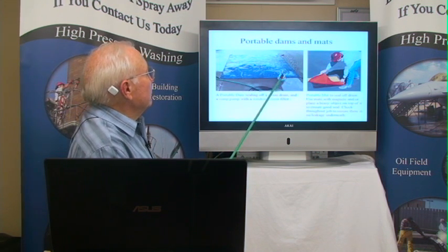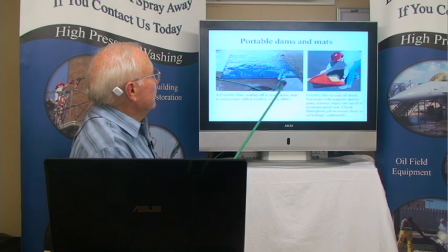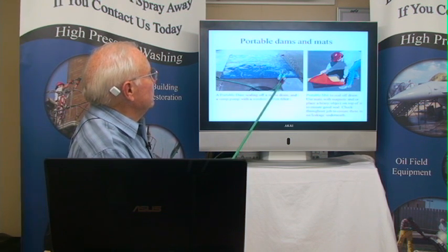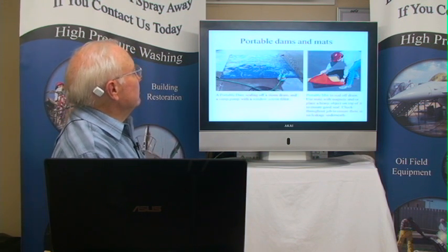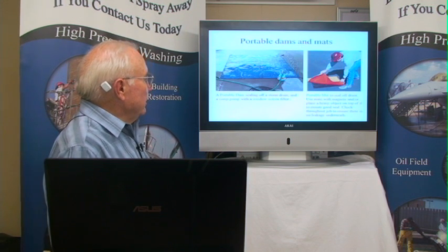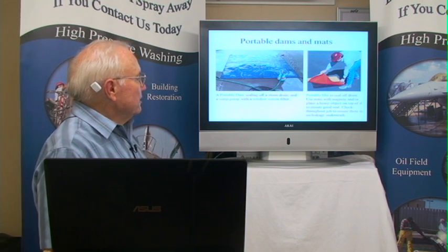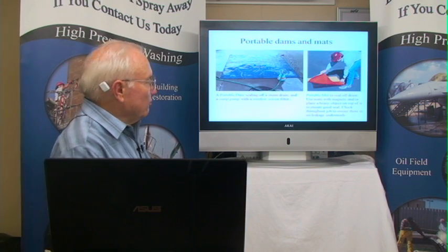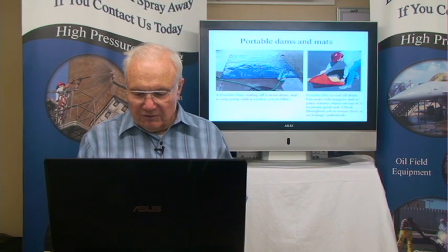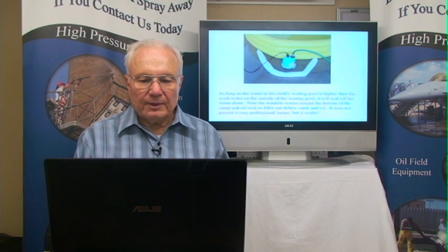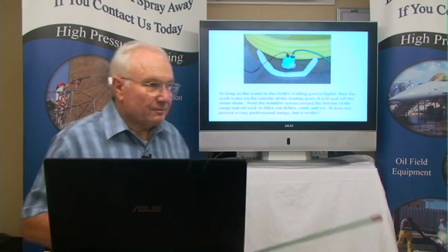This particular contractor has a sump pump, and around the bottom of the sump pump, he has a window screen. So now he's filtering his wastewater, and I've seen a lot of times where they put a hole absorbent boom around here, and that way he can pick up that wastewater, and he's pre-cleaned and filtered his wastewater through an absorbent boom. I think we've got a photo in a little bit that shows that. Oh, here it is. Next slide up.